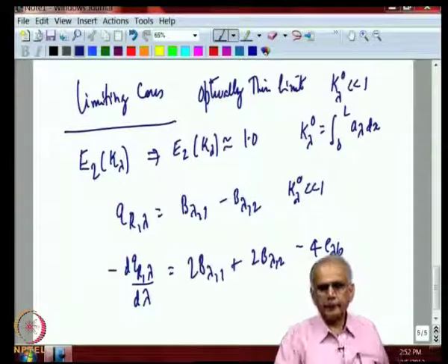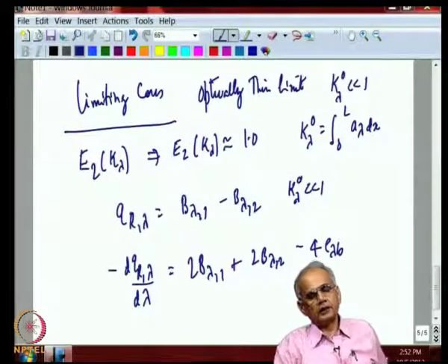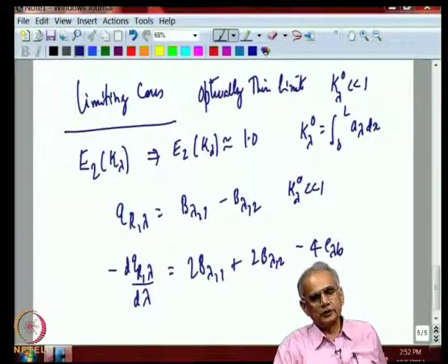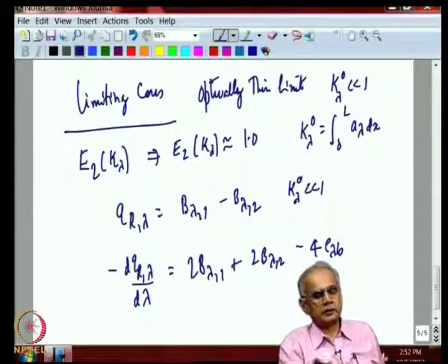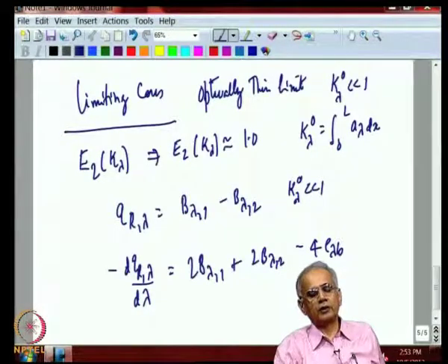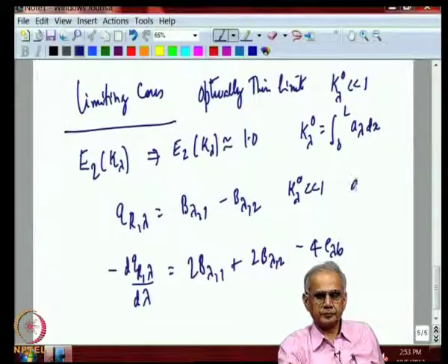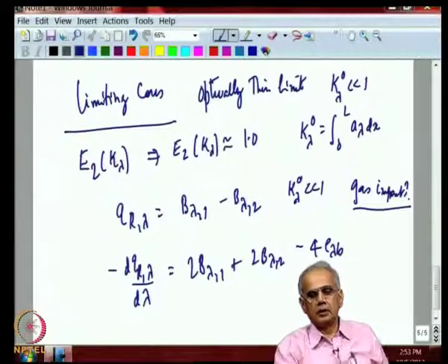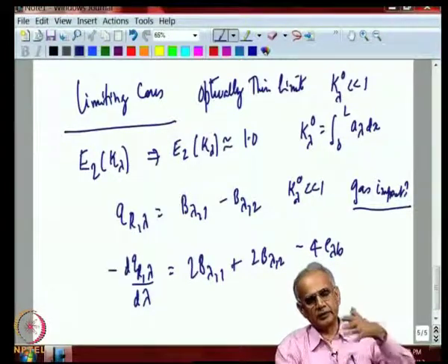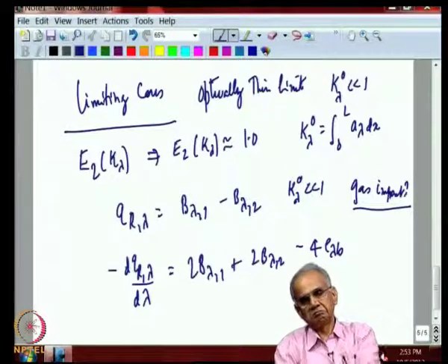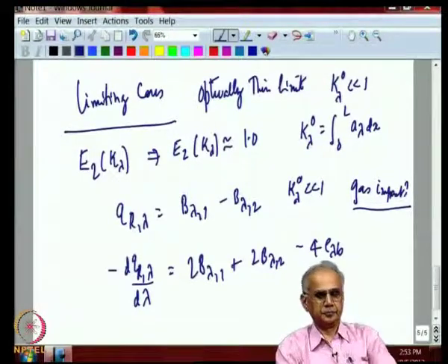So, in the optically thin limit, both the expression for radiative flux and the expression for the divergence of radiative flux are very simple. In the case of radiative flux, you see no impact of the gas. So, the fluxes are being exchanged between surface 1 and surface 2 without measurable deviation.